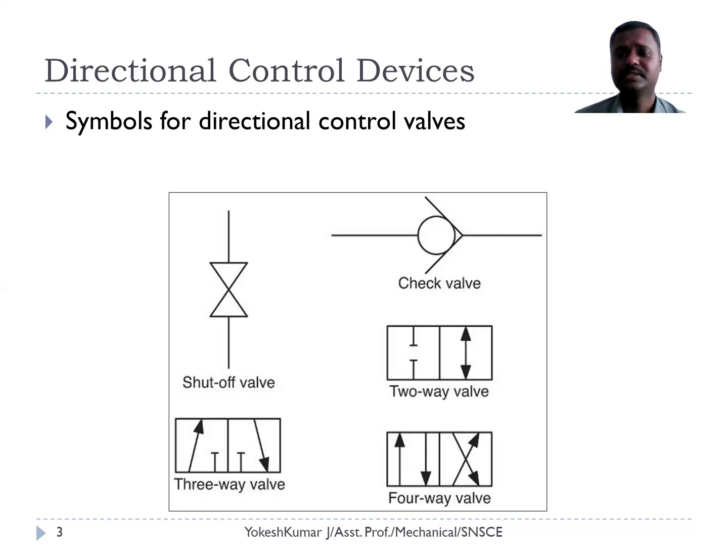These check valves are typically found in submersible motors, open well motors, and centrifugal pumps. The centrifugal pumps need to create a vacuum based on the fluid storage. So the foot valve is used to avoid reverse flow. That is, the flow from the tank cannot be reversed to the well with the help of the check valve.